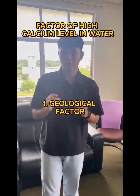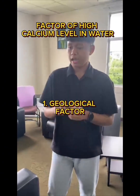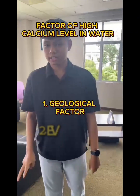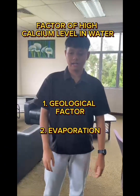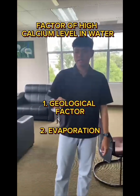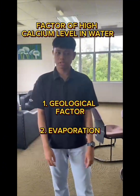When rainwater or groundwater moves through limestone, a calcium-containing mineral, it can lead to high calcium concentration in the water. Areas with limestone or other calcium-rich geological formations are more likely to have high calcium level in their water. The second one is evaporation. In places where water evaporation rates are high, the remaining water may become more concentrated in dissolved minerals like calcium. As the water evaporates, minerals remain behind, increasing the hardness over time. This is particularly noticeable in lake or groundwater sources.